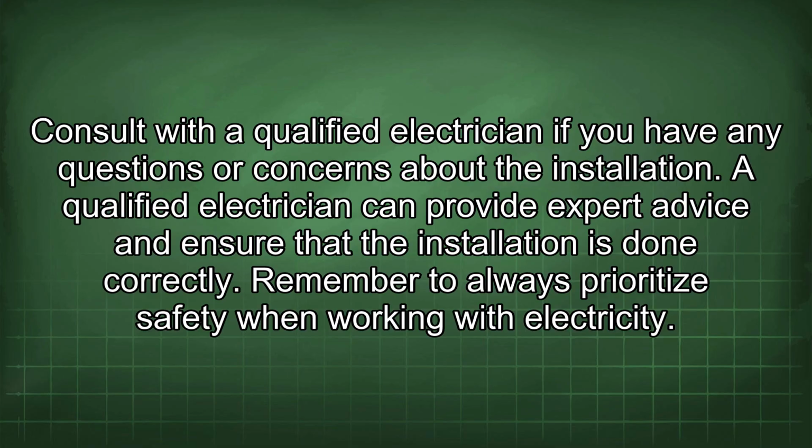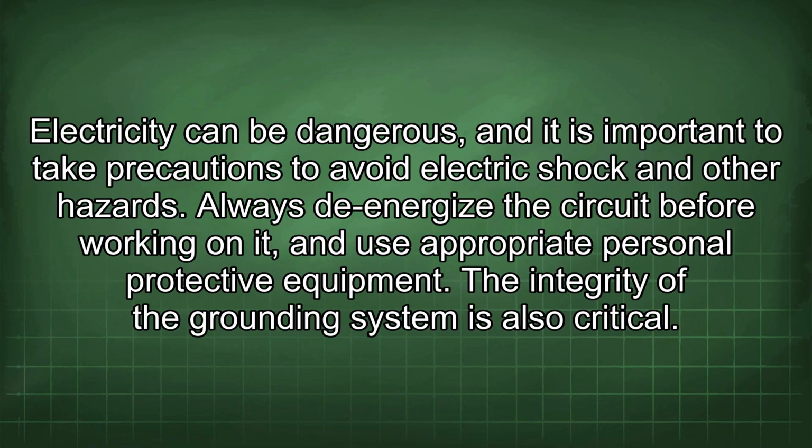Remember to always prioritize safety when working with electricity. Electricity can be dangerous, and it is important to take precautions to avoid electric shock and other hazards. Always de-energize the circuit before working on it, and use appropriate personal protective equipment.